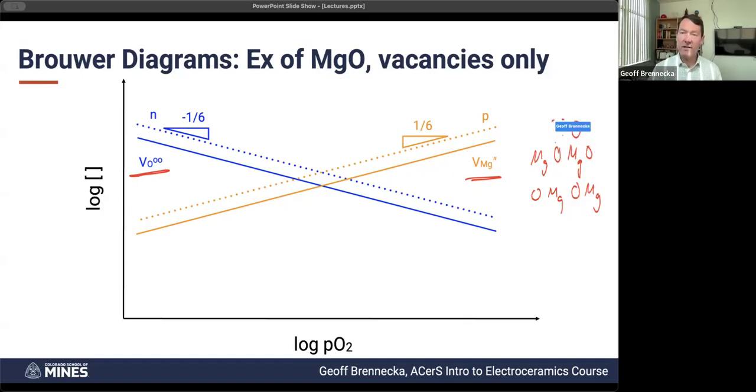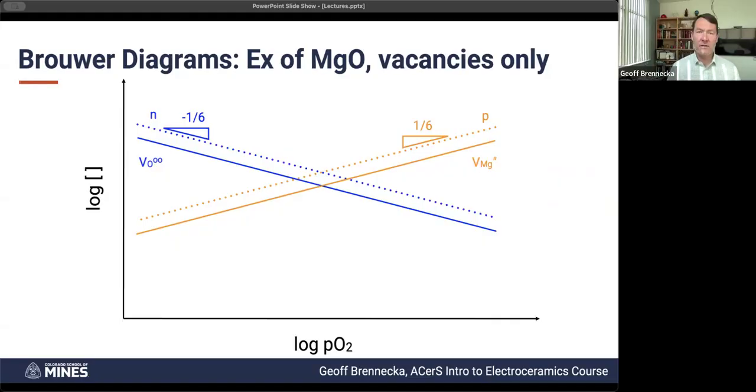And the equivalent is having a magnesium vacancy, because there's no extra magnesium to make up for having that extra oxygen hanging out there. And we just refer to that as a magnesium vacancy. Hopefully that makes sense. So any further questions on these kinds of scenarios?